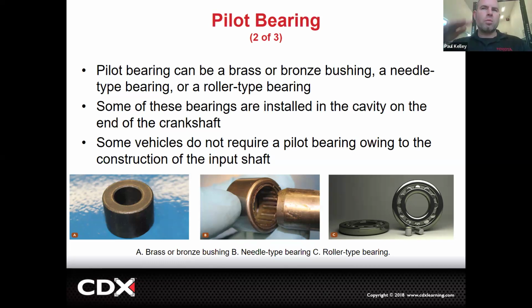That way, when you push your clutch pedal down and your engine spins, including your crankshaft, the bushing spins, but your input shaft stops. And so the bushing going around your input shaft is not going to wear it out. It's not going to gall it, right? We'd rather have all the wear go into that bushing than into your input shaft, your transmission, and have to replace your transmission. That's the real purpose there. So we could use a simple bushing. Those would need to be greased, by the way. That's part of the job.